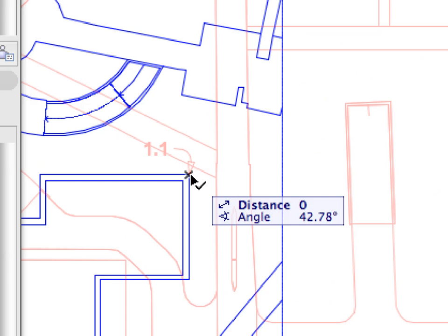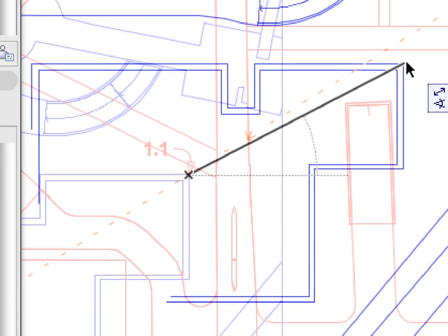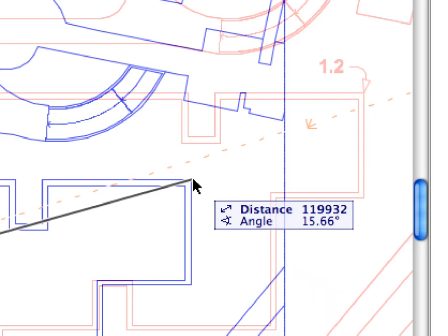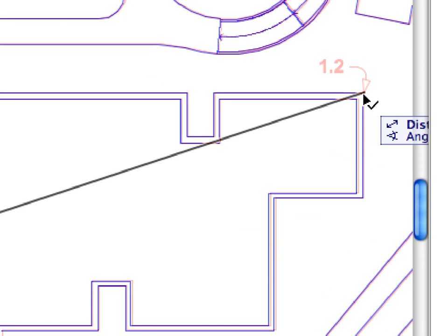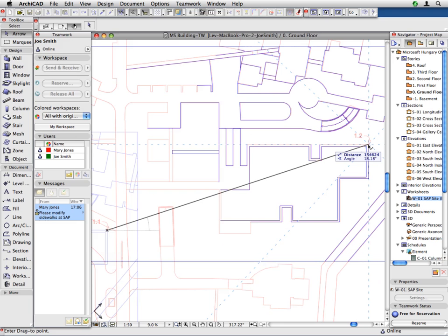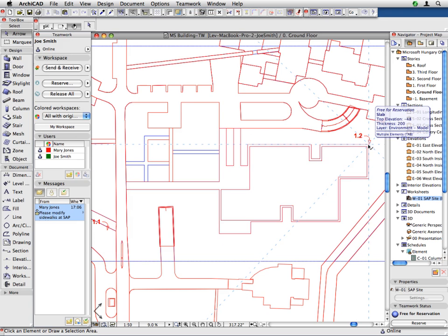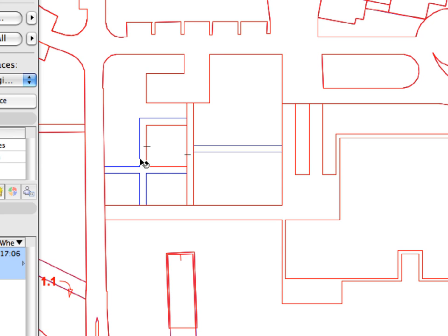First, click the point of label 1.1 and then the point of label 1.2 to drag the landscape trace reference to match it to the site plan. The landscape reference drawing has now been placed at its correct location and neatly overlaps our site plan drawing. The only lines you see in different colors are those lines in the trace reference which we need to update on our site plan.